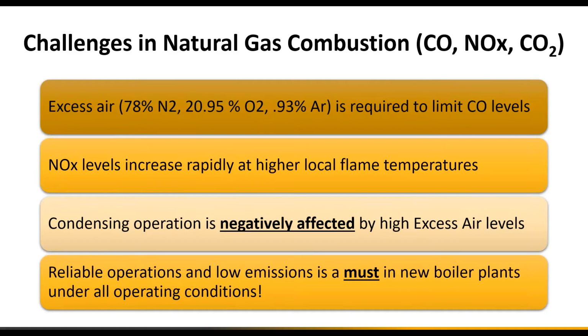Another challenging factor is if we have a lot of excess air. So you may think, okay, we need excess air, put in some excess air. We'll keep our flame temperatures low. Our NOx levels will be low. We need some excess air to reduce CO, so that's good. Well, if we put in a lot of excess air, what we're really doing at that point, if you think about a hot, muggy day in the summertime, and you're adding just clean air, not moist air, dry air, we're drying out the air.